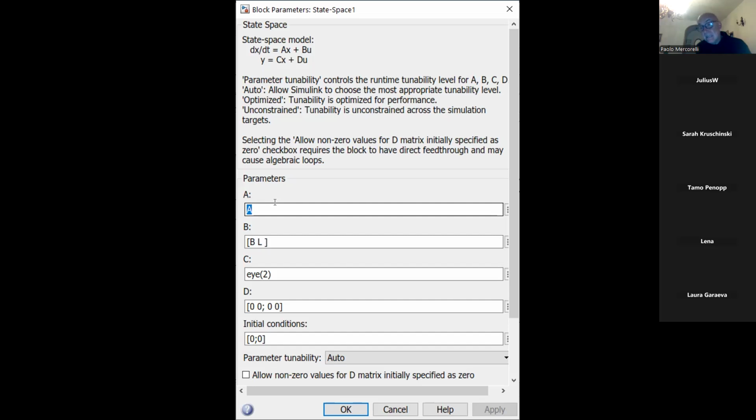But the input is characterized, we have two inputs, excuse me. One channel, let me say, of the input is characterized by the matrix L. I will invest today 10 minutes, 15 minutes, on the matrix L a little bit more. C is an identity matrix because I would like to have the possibility to see not only x1, but also x2. x1, I need to build the observer. x2 in order to verify, to validate the observer.